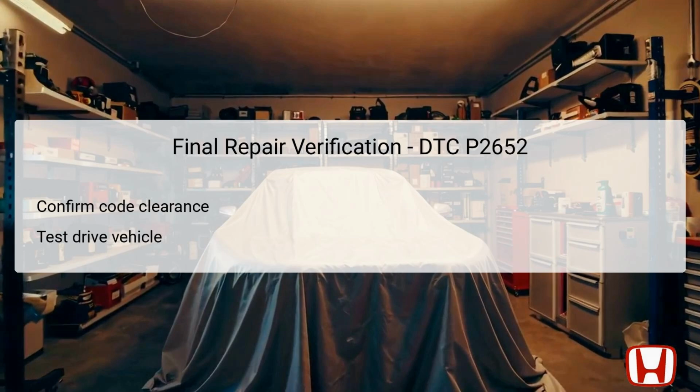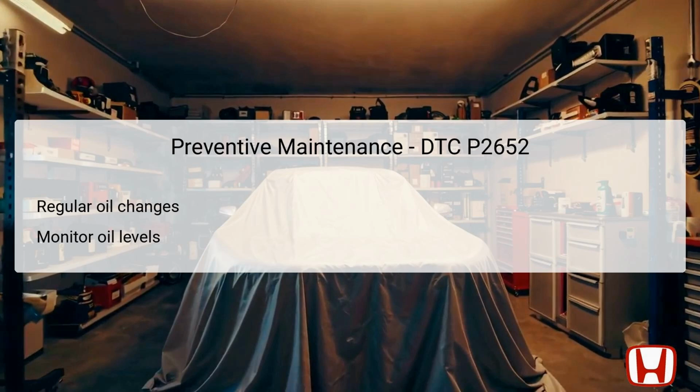repairs were successful. Implementing preventive maintenance strategies is essential to help minimize the occurrence of DTC P2652 and similar issues in the future. Regular oil changes, as per the manufacturer's recommendations, ensure that the engine has optimum lubrication, preventing overheating and maintaining the integrity of the rocker arm oil pressure switch.